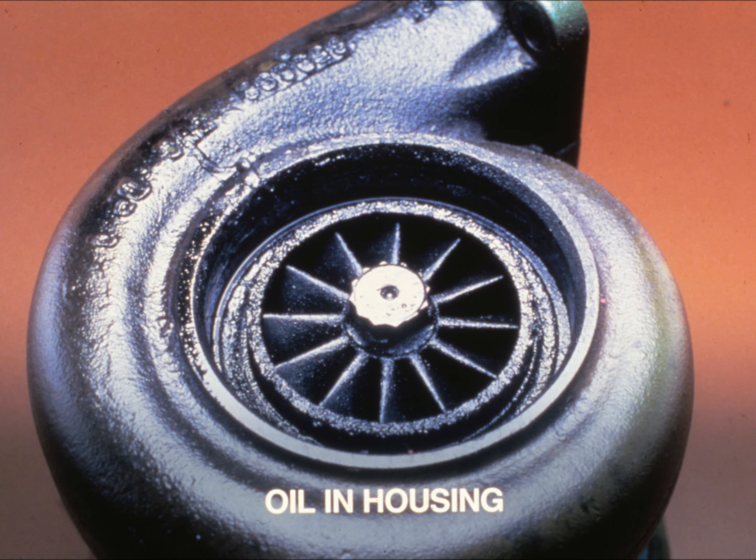This type of failure can result from certain operating conditions. If the engine is idled for long periods or operated under light loads, unburned fuel can be expelled from the engine. The appearance of the fuel as it slobbers out of the turbocharger is similar to an oil leak. This condition should clear up when the engine is placed under load.